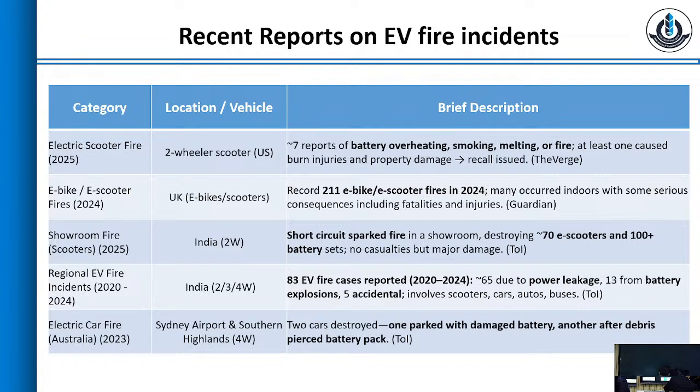Mostly these electric vehicles are charged indoors in the basement, or they are in the showroom. So they are not in an open environment, but a closed environment. And then you have showroom fires in India. For two-wheelers, around 70 e-scooters plus 100 plus battery sets were in the showroom, and they got damaged. The reason for this you also have to notice: it was not because of battery failures, but because of some electrical failure, is what was reported. That triggered it, and batteries being combustible because they have oxidizer and hydrocarbons can burn severely.